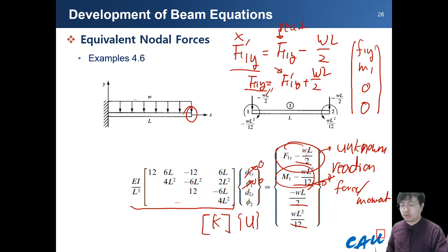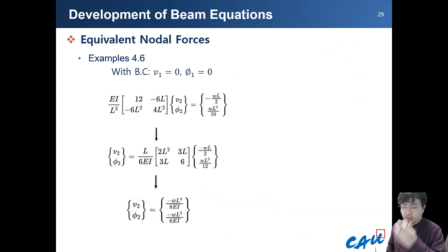This is in the explanation of the previous slide. So anyway, let's check more detail. After we apply the two boundary conditions, fixed in the y displacement and fixed rotational movement here, then after applying the boundary conditions, we obtain the reduced 2x2 matrices here.